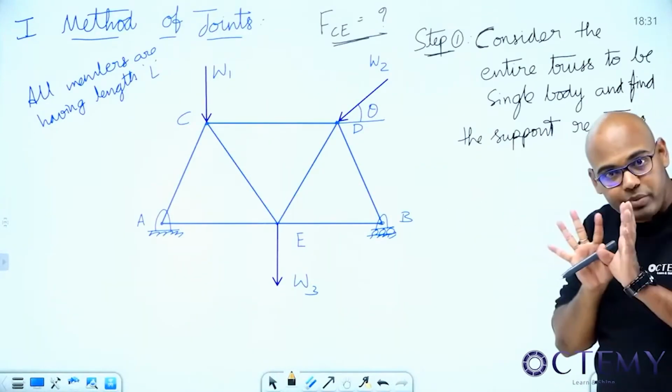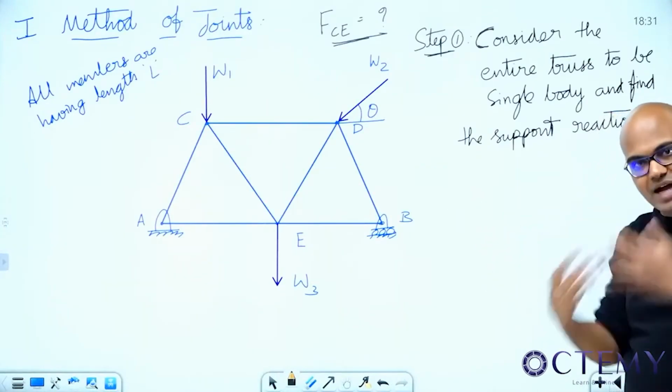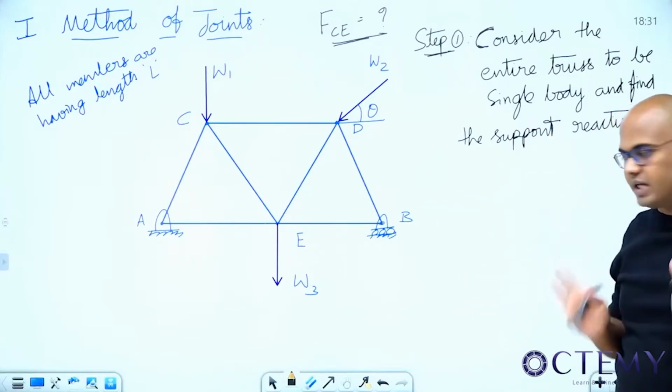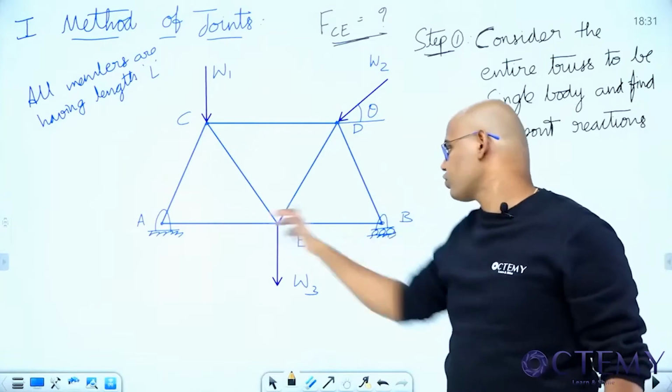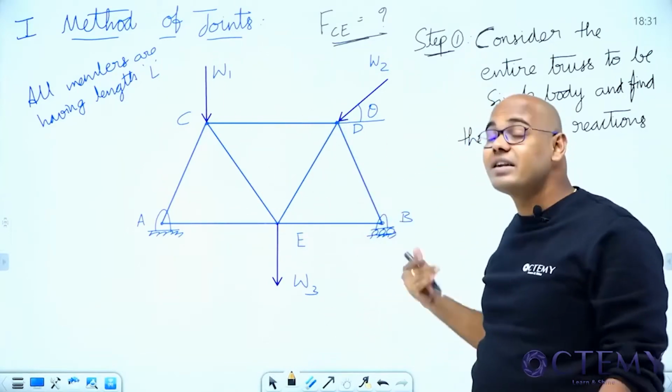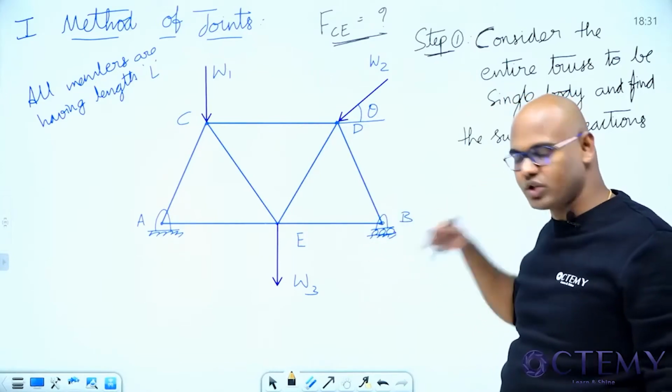Sir, he has not mentioned any masses because we are treating them as massless, right? All are rigid. At every joint it is frictionless. So free the body from everything and draw the sketch. Done. Three loads at C, D, E taken. Next, reactions. Actions done, sketch done. Go for the reactions.